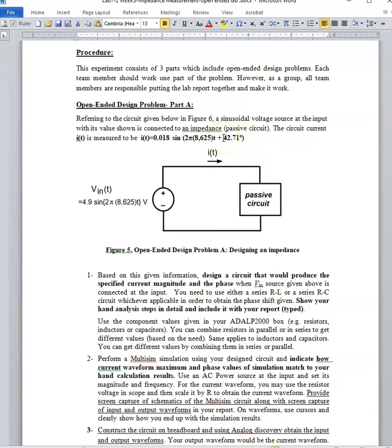What you need to do is just get the impedance calculated once you put the voltage and the current in polar form. So once you have this represented in polar form, then you can get the impedance Z. It would be something like maybe 120, 60 degrees, something like that.